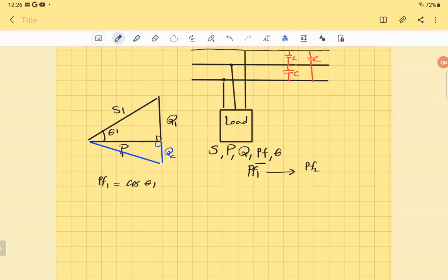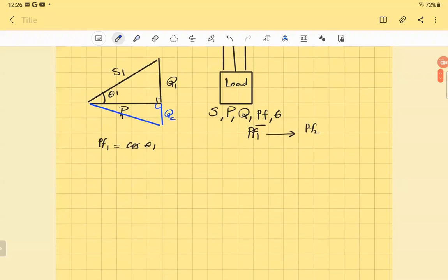He said something good. The current from the capacitor is going to affect everything. But there is something. We know that the current is not only magnitude. Any current in AC is like a vector, has a magnitude and a direction. So there is a real part, you can call it IR, and another part is called IX. It has two components. So what do you expect? The capacitor does not have resistance, so it's only supplying reactive power. So the current is not in the real direction, not in the X direction. It's always J. It's always perpendicular, as you see. So it's not going to affect the power.